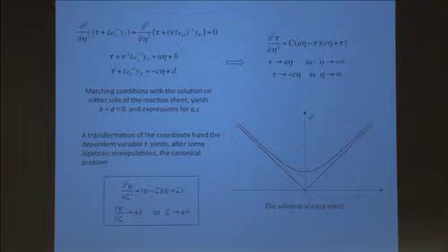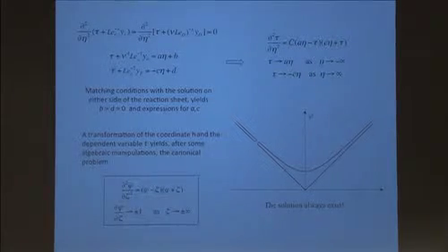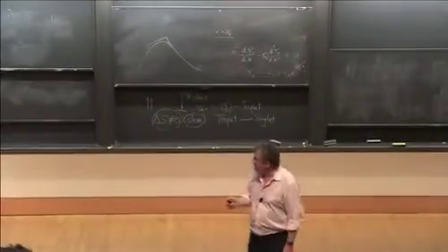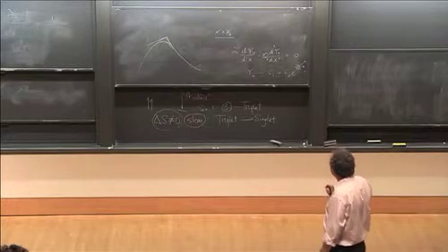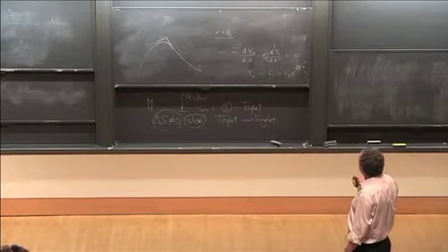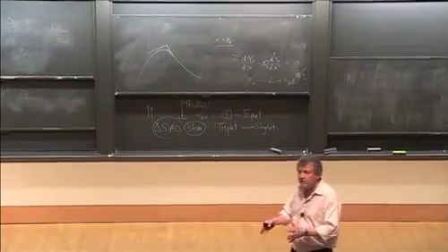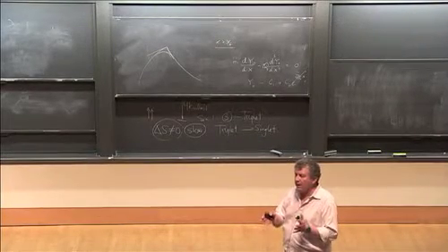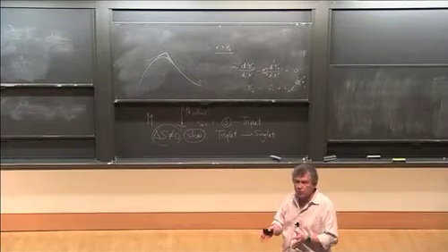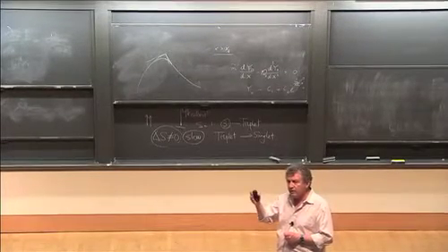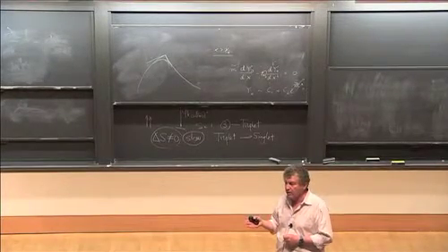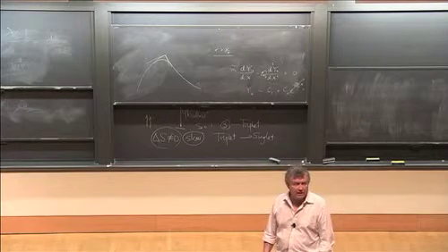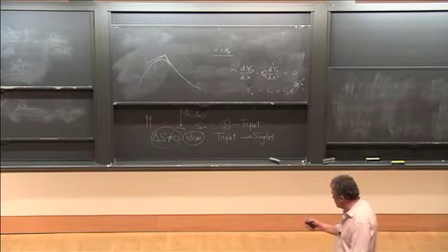In other words, it makes a nice, smooth solution of the temperature through the reaction sheet, right, through the reaction zone. Essentially, what this says is that a solution always exists, and therefore the Burke-Schumann solution is a good solution in the limit when the Damköhler number goes to infinity. Okay, it's a solution that always exists.